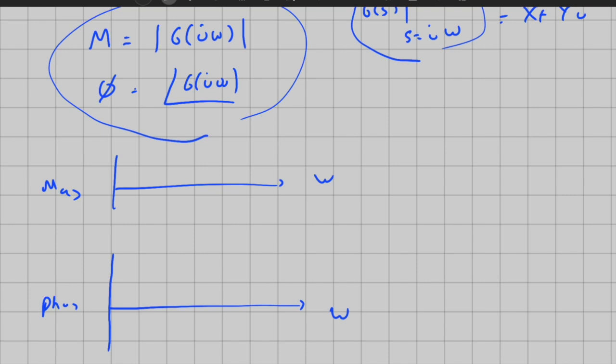It's okay, but you cannot capture important details, and high pass and low pass filters can look very different from the perspective of a linear frequency scale. Instead, we use a logarithmic scale for the frequency. We use the original units, hertz or radians per second, but we label the frequencies in terms of a logarithmic scale.